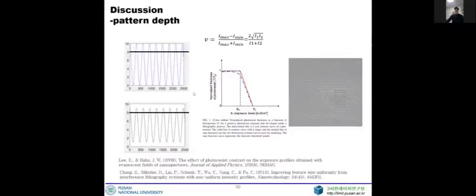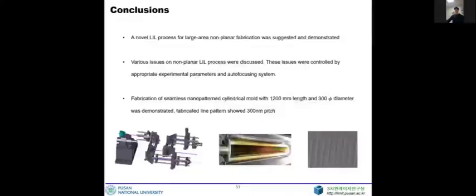Also, because photoresists have a kind of threshold for exposure dose, a little change in contrast can be a significant error. To solve the low contrast issue, it could be considered that the laser beam size must be larger than in this experiment, and a higher power laser or beam homogenizer must be used for more uniform intensity distribution.